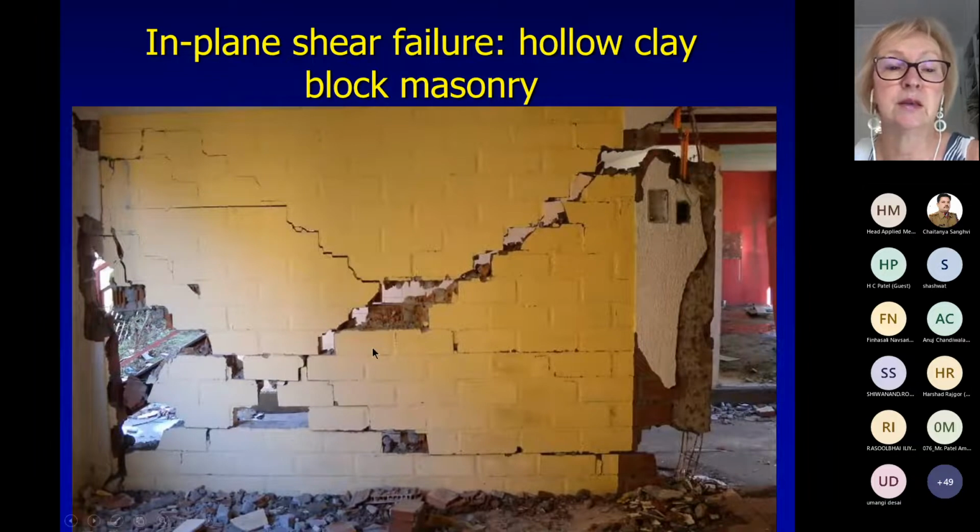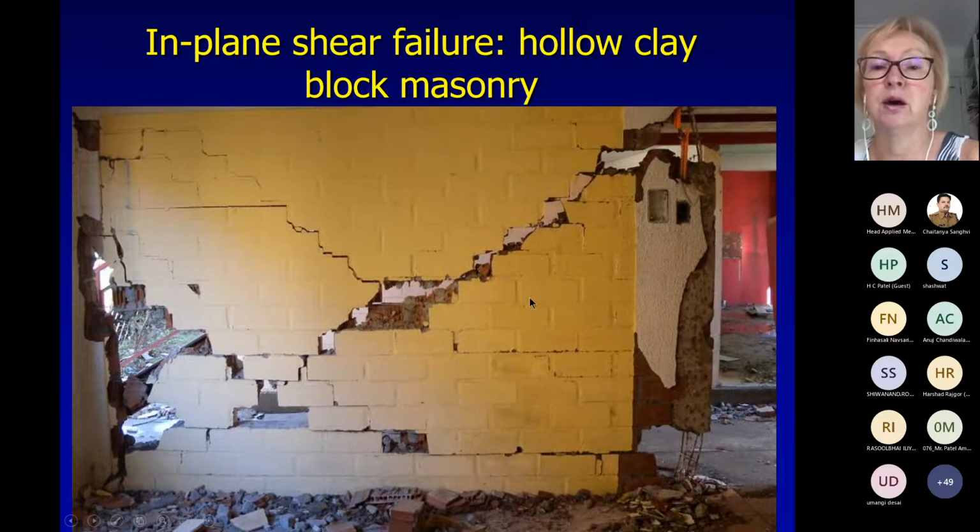This is inside that same building. You can see that even interior walls, which were also of confined masonry, suffered extensive damage. Again, you can see the damage of these hollow clay blocks. You can see that parts of walls were missing.